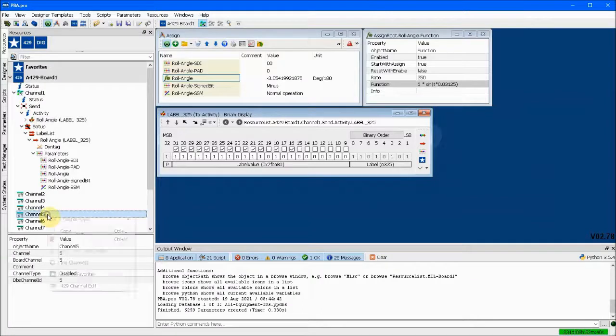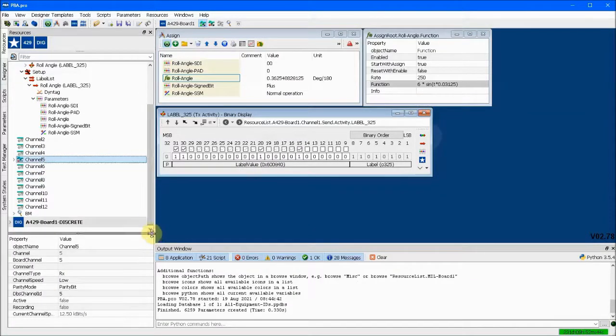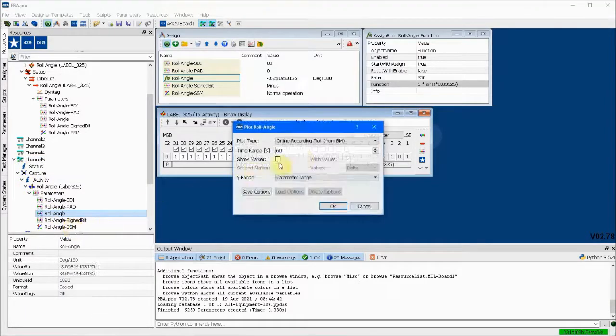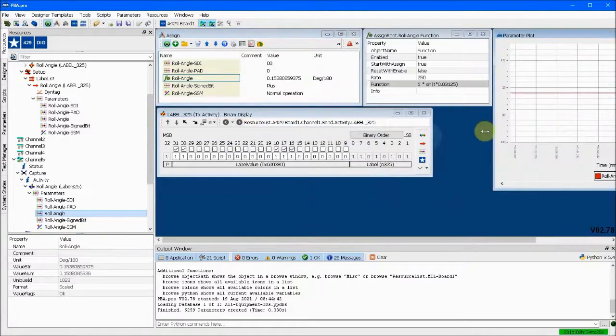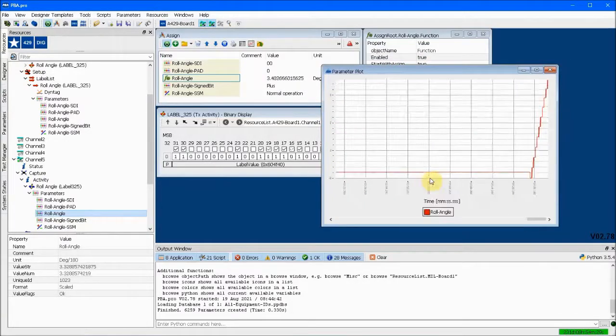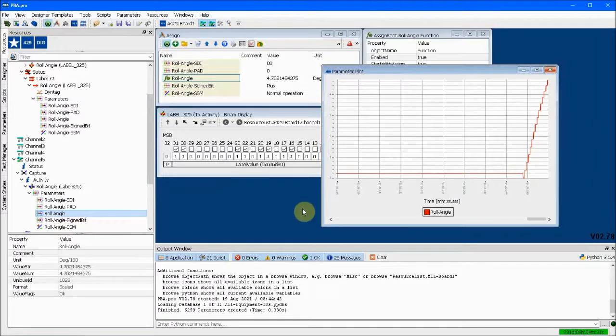We can turn on the receive channel 5 and switch its database channel ID to 42, just like we did for channel 1. Then start the receive channel and look at the activity. In this case, we want to see a plot of the incoming data. Selecting auto-adapting Y range gives the proper vertical extent for the plot.